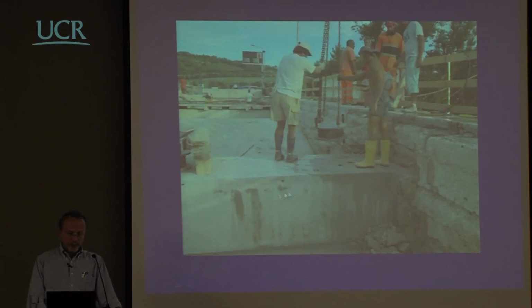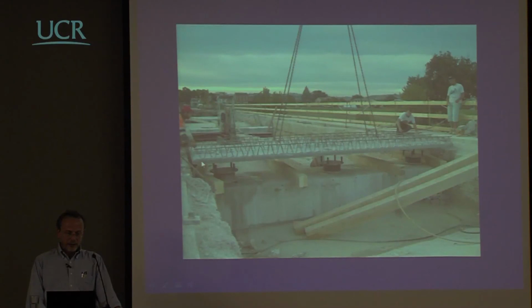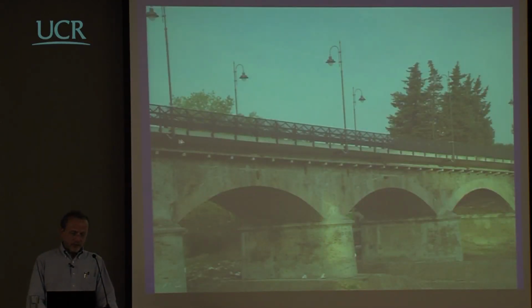And you can see here one of the transversal steel concrete beams, and this is one of the isolators which is going to be mounted here. And this is just the lower part of the cast, the form that will be left there anyway, which is mounted on top of it. And this is what you obtain at the end. And this is the gap between the two bridges, the concrete one, which is an isolated bridge, and the masonry bridge that in this case becomes simply a reminder of the past, because there is essentially no load on top of it. There is only its own self-weight.